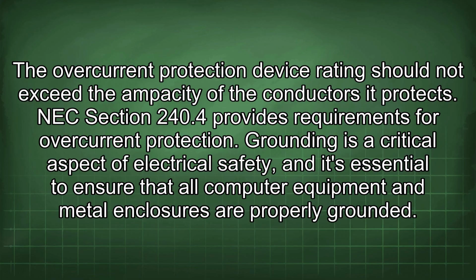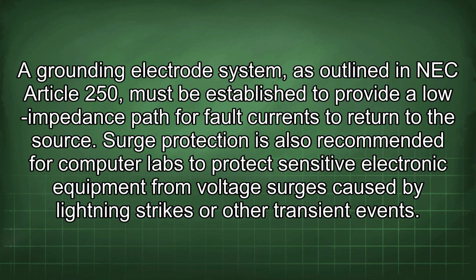Grounding is a critical aspect of electrical safety, and it's essential to ensure that all computer equipment and metal enclosures are properly grounded. A grounding electrode system, as outlined in NEC Article 250, must be established to provide a low impedance path for fault currents to return to the source.